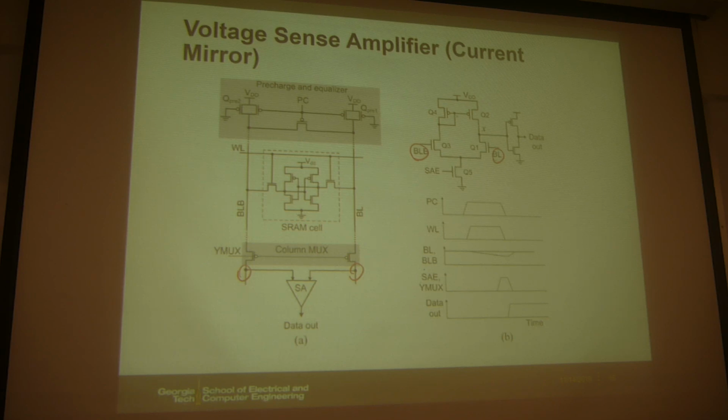And then this is a current mirror, PMOS as current mirror load, and then you convert the differential input to a single-ended output from this node, and later you can further follow it by an inverter to clean up the signal to drive this out. So this is a very simple design. I hope that with this simple circuit you can understand this if you take any undergrad level analog circuit.